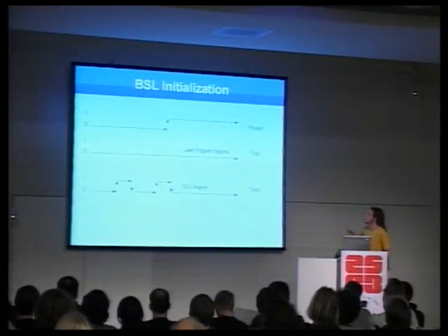If you send 2 pulses, and sometimes this is backward on another pin, if the second pulse falls just after the reset line goes high, then instead of pushing the reset vector into the program counter, it pushes a vector found within permanent masked ROM.